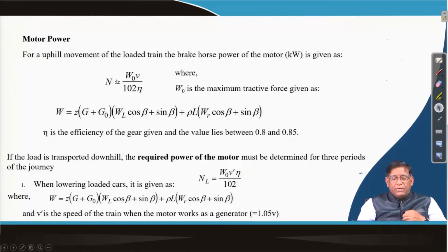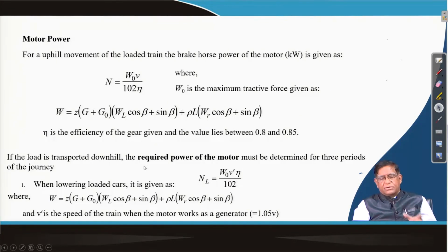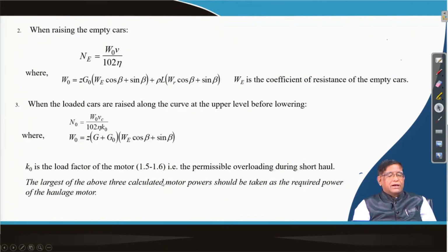And if you find out the efficiency, then for the system you can select a motor by considering the efficiency of the motor and the efficiency of transmissions in the gearing and all. Taking that, you can calculate the motor power. These equations are very simple, you can easily derive them, and then you can do some small calculations.